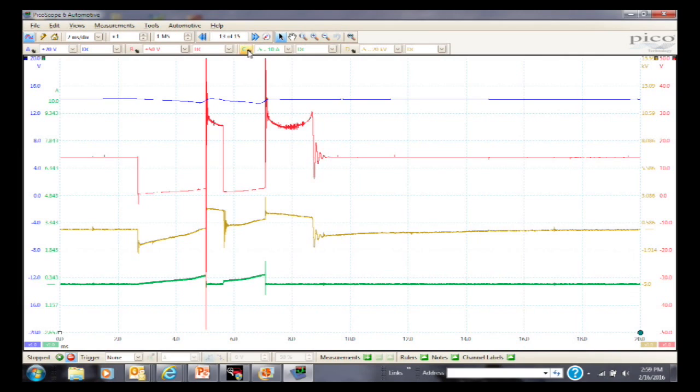So channel D is our ignition secondary. This is our secondary right here in tan. And this is a mirror image. You see these look just like each other. Actually, that looks bigger, but if you look at the actual voltage scale over here, it looks like we're at maybe about 500 volts right now, and it spikes up to about 3,000 volts. So this was a few hundred volts, 50, 100, whatever. This is a few thousand volts. So we have different scaling here, but you can see the patterns are the same.